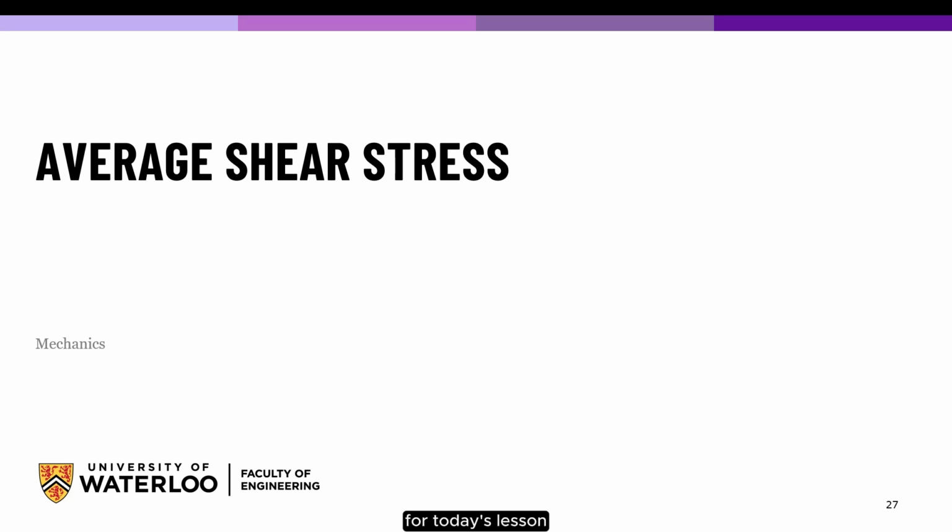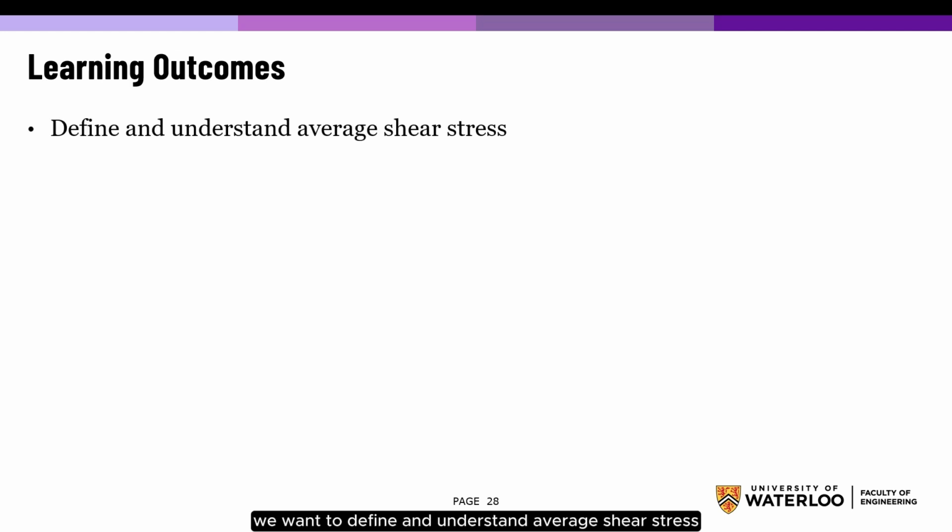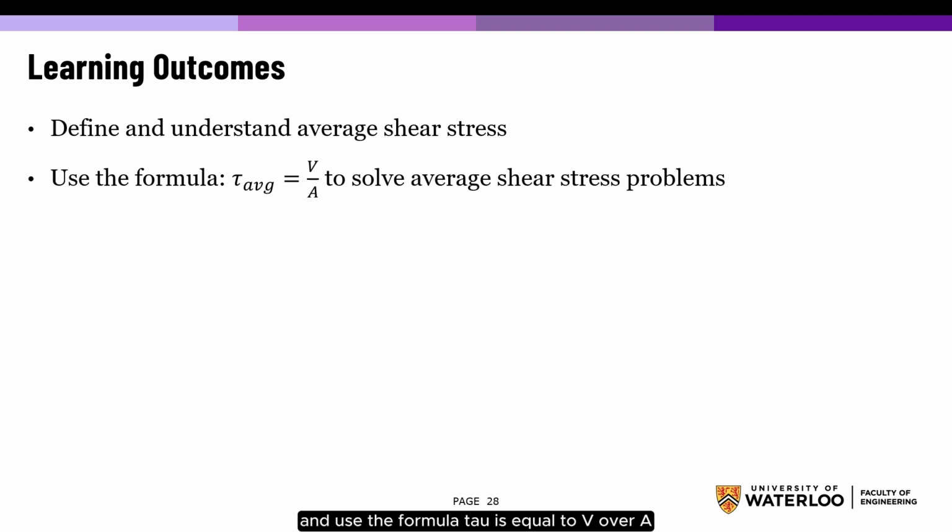For today's lesson, we will be going over the average shear stress. Let's look at some of the learning outcomes. We want to define and understand average shear stress and use the formula tau is equal to V over A to solve average shear stress problems.